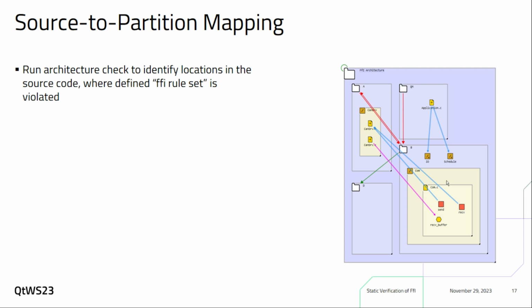And that causes this red edge, so this divergence of QM accessing into the level B. And there are calls from some source file inside of this CAN driver, apologies, in the other direction, from the com.c receive function to some function that is declared inside of this header, causing this red edge shown here, so that B has an illegal access into the level A. And this illegal access is according to the rule set that was defined in your safety architecture, or in the rules given in this previous slide.